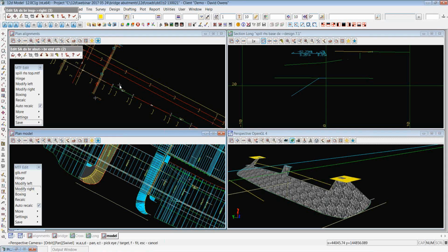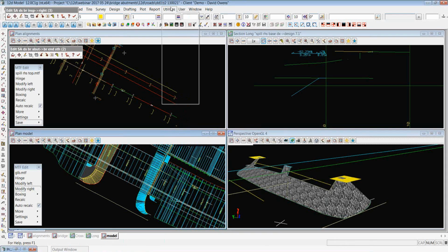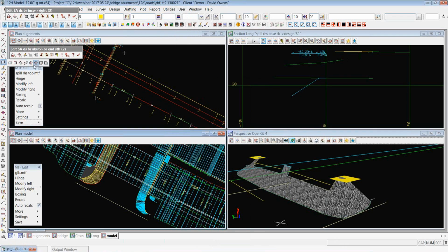So I would just plot them both onto a long section and just do a polygon discovery to generate a polygon on the long section plot and then calculate an area from there. Just in case you guys weren't aware, there are some really cool options for getting boundary polygons of data, both in utilities ADG and in the CAD section. There's a polygon discovery, where we just pick a point, drag it out, and it creates a polygon area.